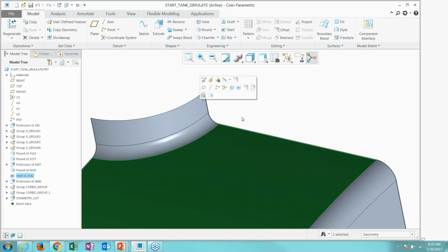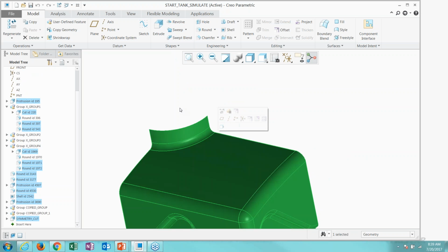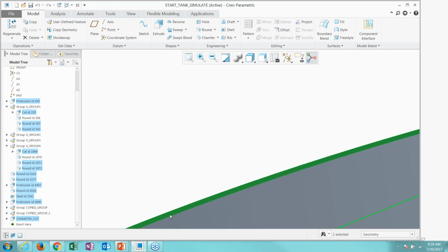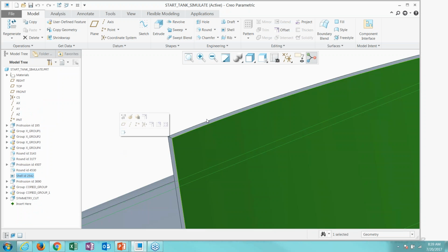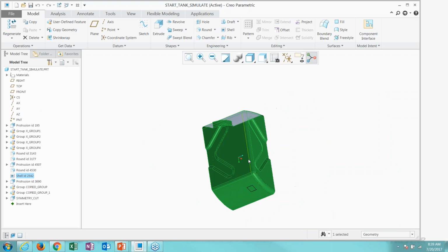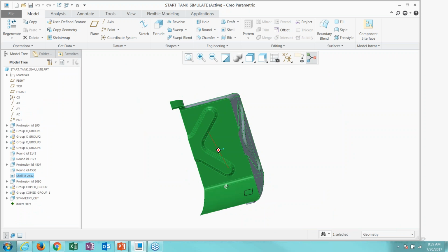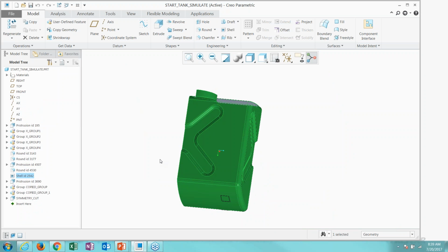In such situations, we don't want to be using the Control key to select several hundred surfaces. All you do is select the seed, and then you hold down the shift to grab the boundary. So it bounds at that. I'm going to just do another boundary here, and another boundary. When I did that, you see how I got all the inside surfaces only, because that thin side surface was the boundary. It selects everything between the seed and the boundary except the boundary, right?